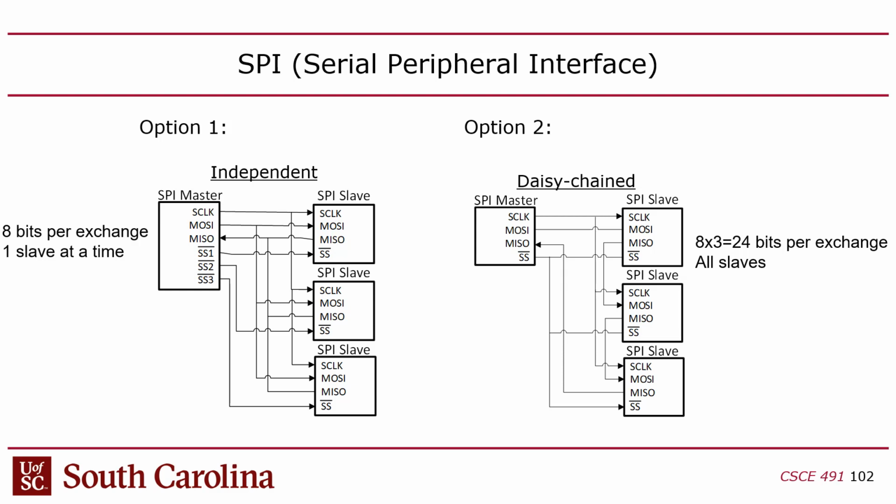They all have to be putting a 1 or 0 onto that output. And the problem is that if you have one driver that's trying to drive 0 on a wire and another one that's trying to drive 1, you end up with a conflict.